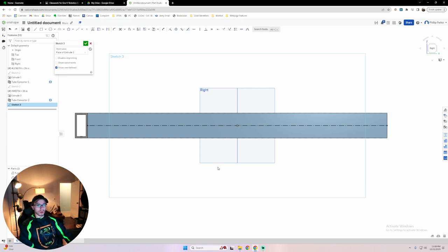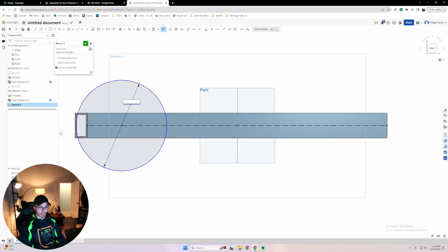So, what we're going to do is we're going to make some bearing holes. Bearings are a standard size. Bearings are 1 inch and 1/8 for hex bearings, which we use. So they're 1.125, right? But I don't want to type it like that. In this case, I am going to type it out.